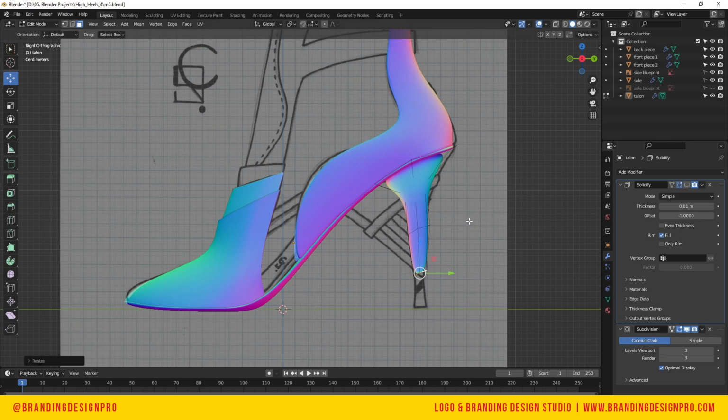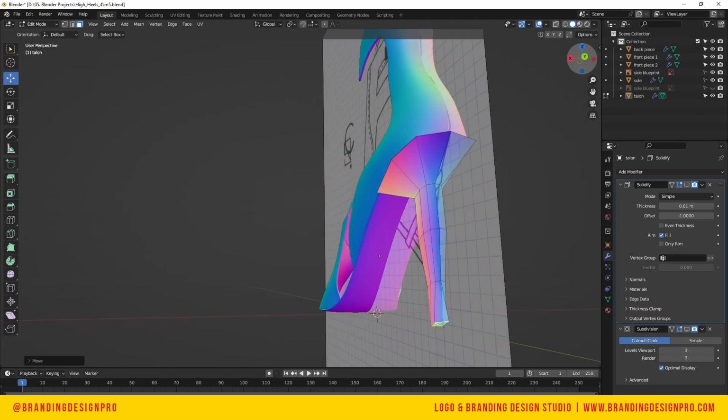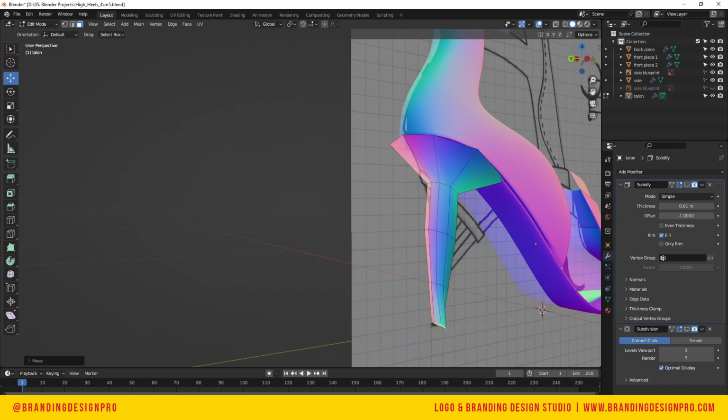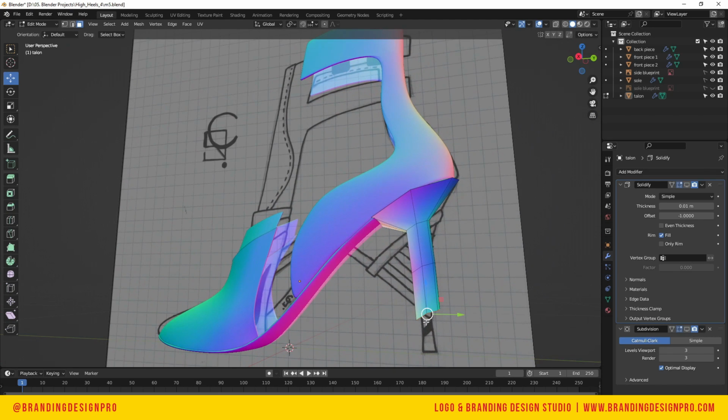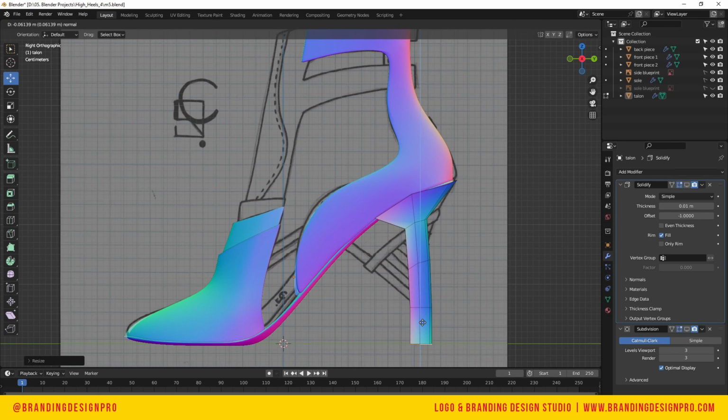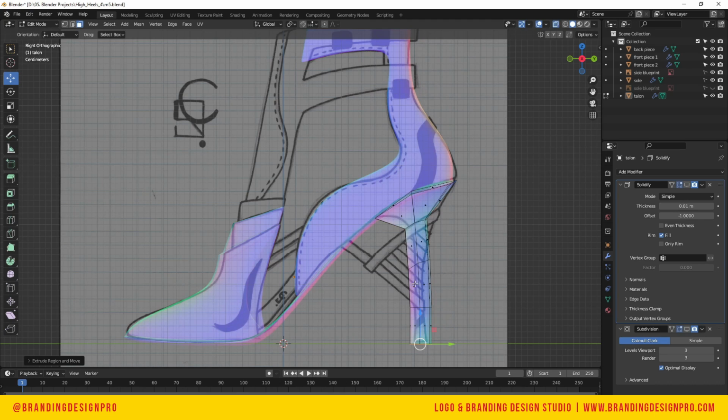Let's hide both the solidify and subdivision. Then E, I don't know what just happened there. What is this? It's so weird. Okay, so let's go back and we're gonna make it flat. So let's go to SZ0, and then now it's flat. We can just GZ, and then do the same thing for these top 2, SZ0, SZ0, to flatten them down on the Z plane, I guess.